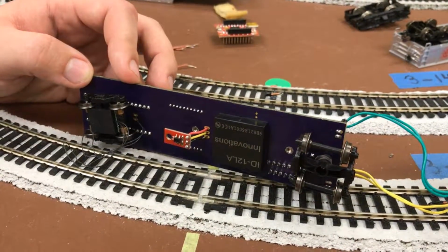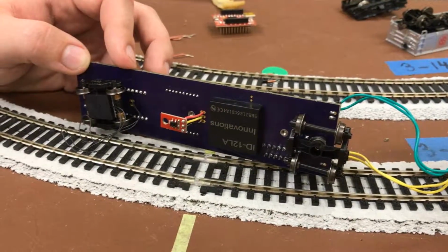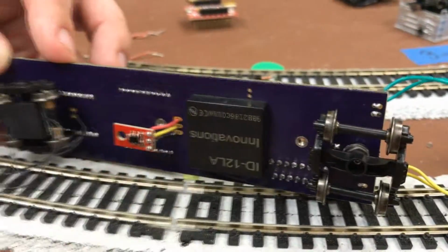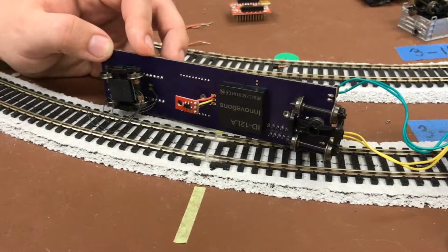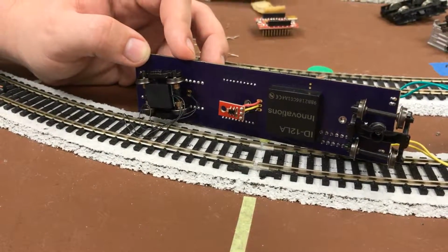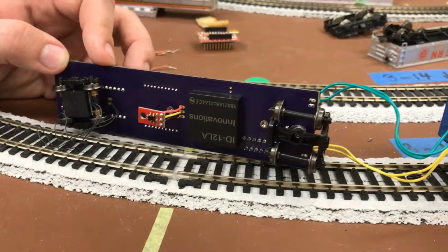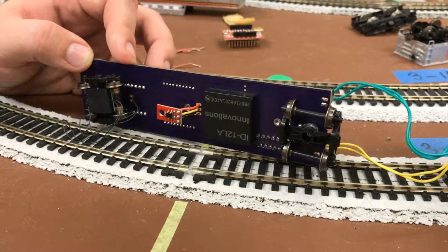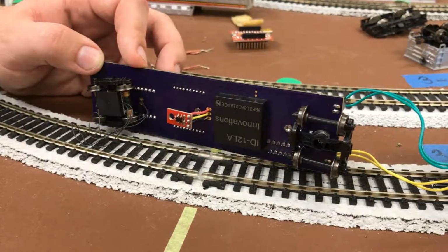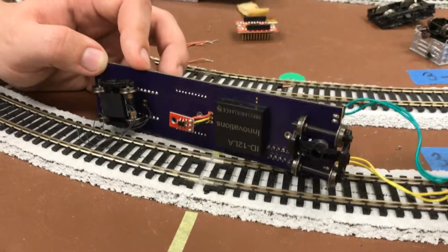For our project, it was requested that we also have a way to track the position of each train. So we have 2 position sensors, the optical tie counter and the RFID tag reader. The optical tie counter is essentially a line reader which is used to signal to us whenever the train has passed over a railroad tie. The RFID tag reader will output the unique address of any RFID tag. Throughout this model setup, there are multiple RFID tags glued onto certain parts of the track that act as landmarks for us to figure out what part of the track a train has entered. With these 2 sensors, it is possible to keep track of each train as they move.